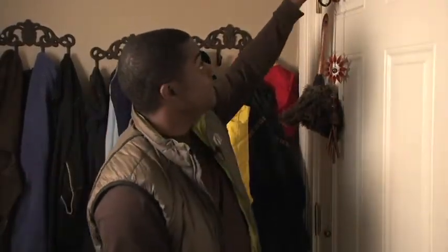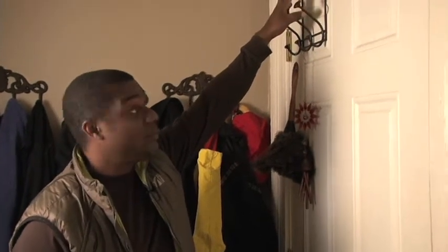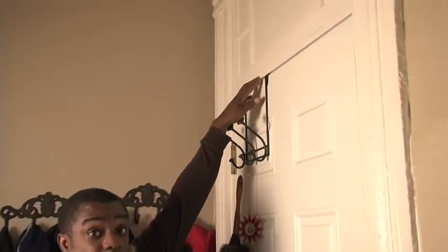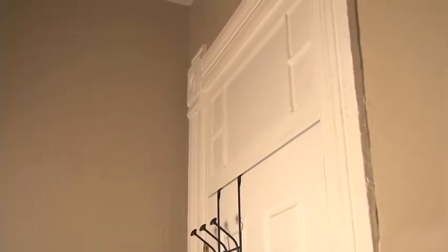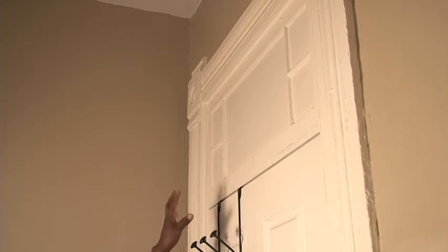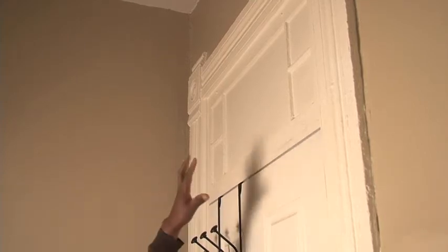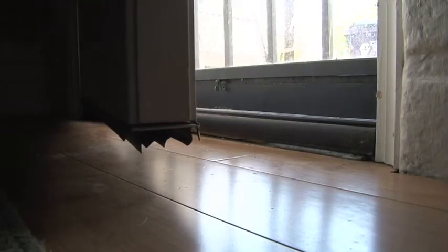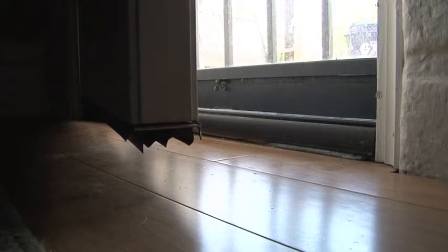Now we also notice that we have something hanging over that front door. And what that's going to do is compress that weather stripping on the inside. And when we run our blower door, likely we're going to see some leaks up there. Up above, we see this transom window. And so it's confirmed, right? We just have a single pane of glass. It's painted over. This area is actually quite dark, so they're not getting any benefit from the light coming in, and they're going to be losing quite a bit of energy out of that window. Down below at the bottom of our door, we want to make sure that we have a door sweep and that that door sweep is installed and in good shape.